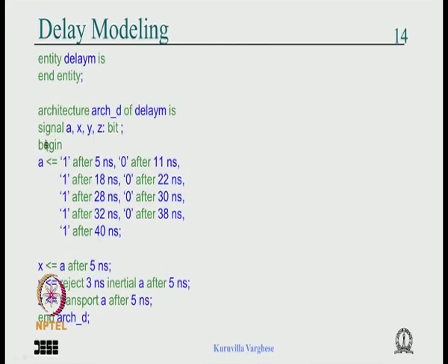So this is a code I have written for simulating that, and you can write this code in any tool and try to simulate, you will get the result. I have not done a demo of a tool, but we will do it in the coming lectures. And first thing to note is that we are only doing a simulation and not a synthesis, because it is just purely simulation. This cannot be synthesized because this talks about time delays and all that.